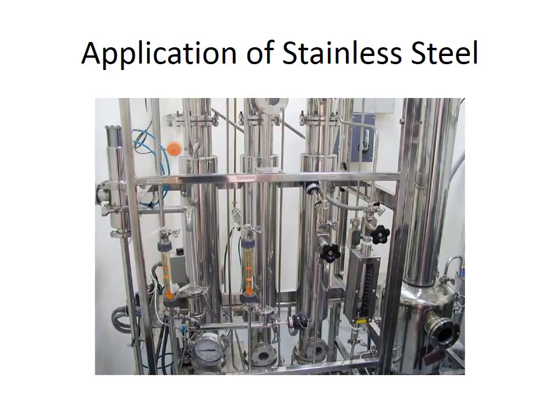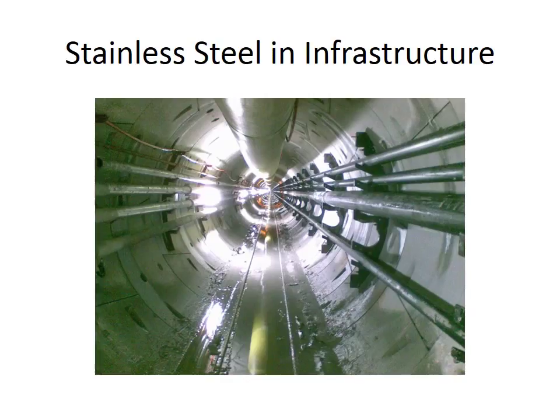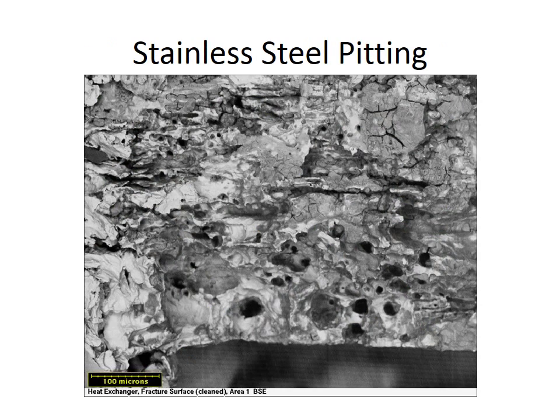The transformation of using carbon steel to using stainless steel in the low-temperature thermal desalination process increased the life of the average plant by 15 years. That time used to be needed to maintain the plants can now be used to increase desalination of more water. This caused greater efficiency of the process, and using thinner lining of stainless steel dropped the weight and cost of the plants. The money saved with this implementation could be used to improve the other parts of the process and can mean fewer risks are involved in the investment in more plants.